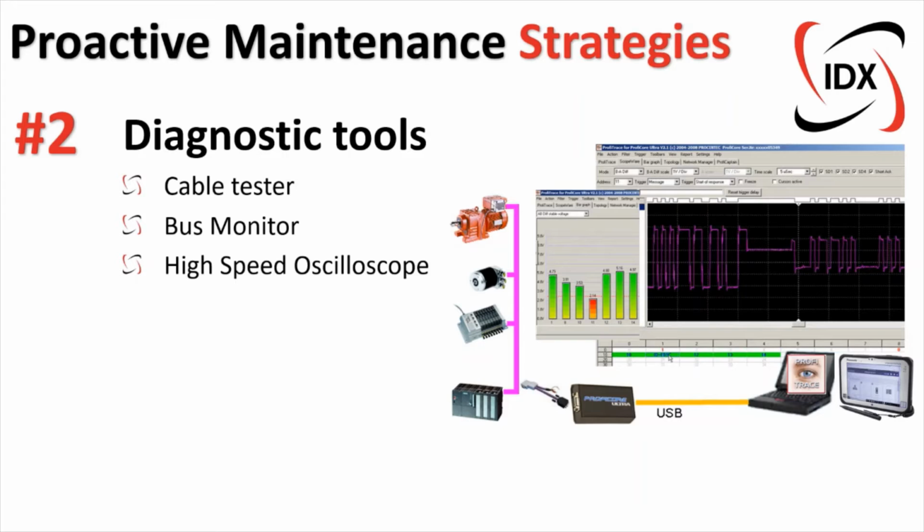The biggest advantage of having an oscilloscope is it gives us a view of the underlying waveform on the network, which is definitely the most key indicator of the overall network health. What you would always expect to see on a PROFIBUS network would be a nice square and even waveform running through the network. A waveform that is distorted or changed from what I just drew could indicate anything from EMI, so interference from high voltage cables and noisy devices. It could indicate wiring faults. It could indicate missing terminations. So very quickly, the first thing we look for is, is the scope healthy and square? If not, then there could be some underlying issues in the network as well.